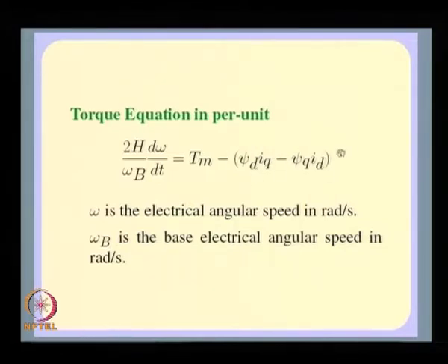Okay. So, when we are trying to use eigen analysis tools, remember that the mechanical and electrical equations are in fact coupled. You see the flux and current terms in the mechanical equations, and in the flux equations there is an omega dependence. Okay. So, because of this nonlinearity, we cannot directly apply linear analysis. Okay. We will have to do a linearization around an equilibrium point.